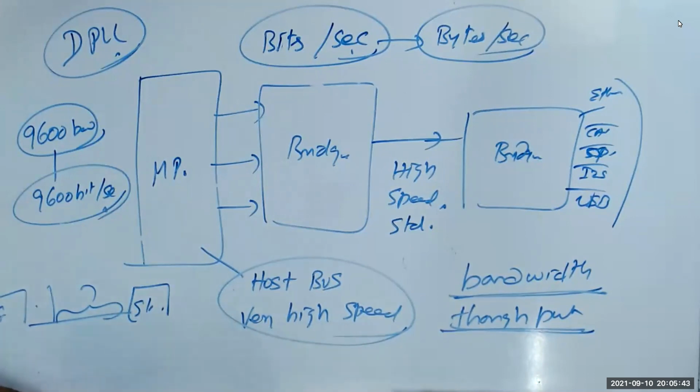I've given a top level discussion about SPI and I2C everything. Next week onwards, we will discuss what is SPI, I2C everything. I2C is a reliable bus. SPI is not a reliable bus. So wherever reliable transfer is wanted, you have to use I2C, not SPI. SPI is only for high-speed data transfer, not for reliable data transfer, because I2C has acknowledgement, which is not there with SPI.